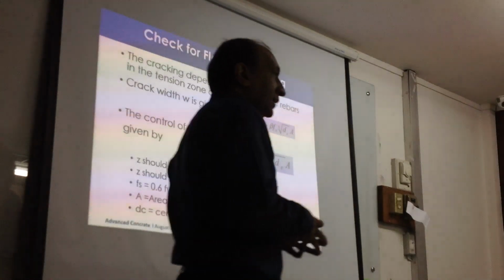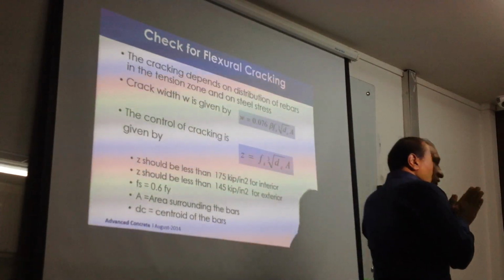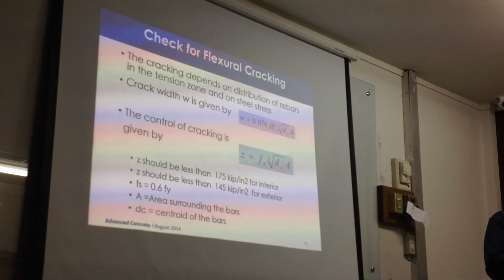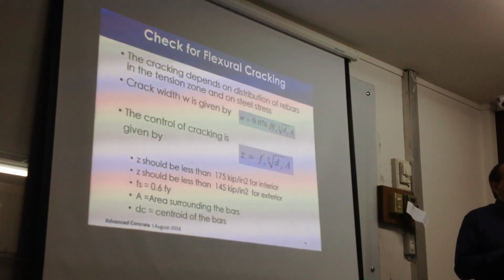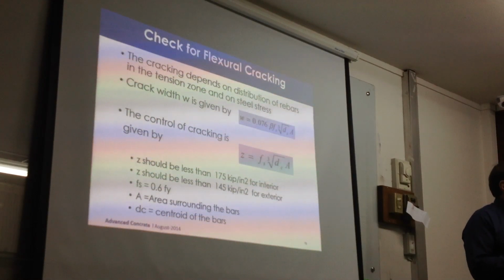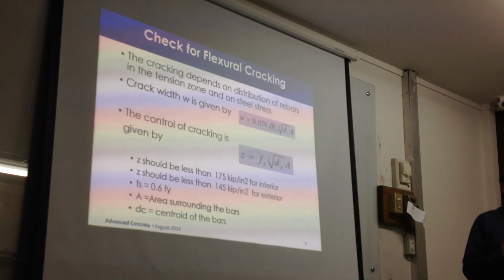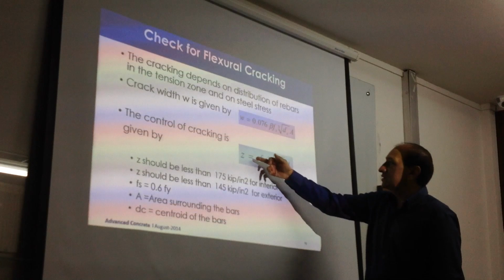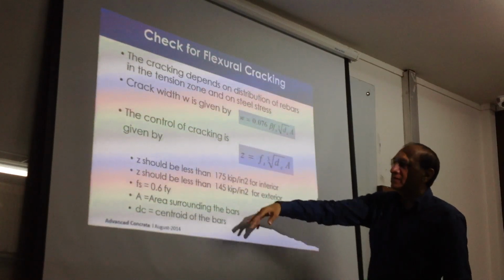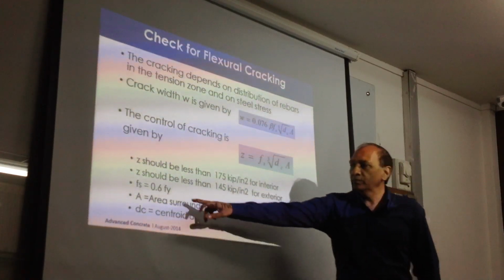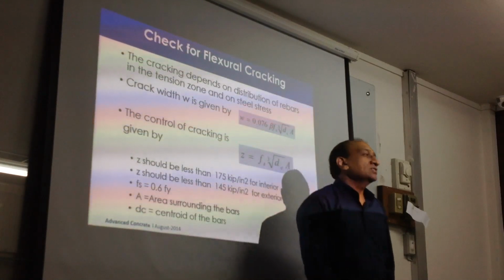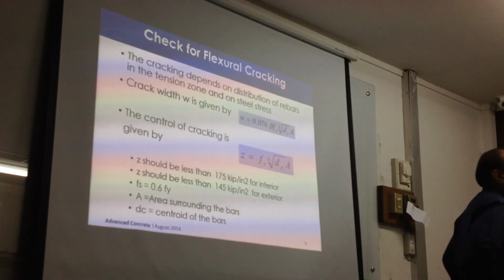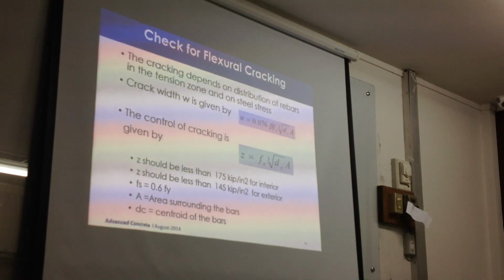Cracking, another issue which is not related to the capacity that we talked about, but section also we need to make sure, in the first lecture I mentioned, check for cracking, deflection and those kind of things. So now we're talking about cracking, right? Cracking is related to this Fs. Fs is equal to something. Working stress method. We go back to limiting the stress, not strain. Now, indirectly limiting the strain, but basically limiting the stress.